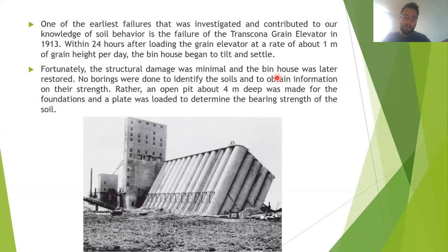You do some stuff to support it, and those are the piles, the Berlin wall, or you can make a diaphragm wall, where you basically drill huge foundations with the excavator, pour the concrete, put in the reinforcement and everything, and then you just dig inside of that wall. For the piles it's the same. Depending on what kind of soil you have and how deep it is, you're going to calculate it.